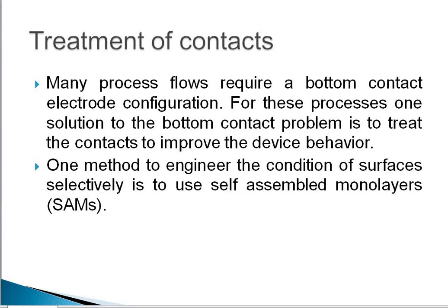Next is treatment of contacts. Many process flows require a bottom contact electrode configuration. For these processes, one solution to the bottom contact problem is to treat the contact to improve the device behavior. One method to engineer the condition of the surface selectivity is to use self-assembled monolayers.